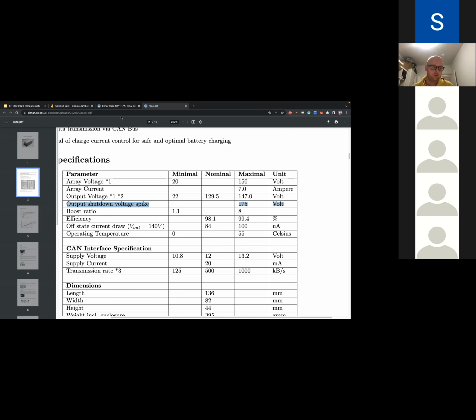I think so. Yes. Thank you. You can select your input voltage by setting a certain PWM duty cycle, and then you can sweep that input voltage to get a little IV curve graph. Then you read that graph to see where the power is highest, see what voltage corresponds to that, and try to stay on that voltage. I think I went a little quick, but hopefully that helps. It already helps, thanks a lot, Elmar. You're welcome. If you want to do a one-on-one and go into more detail, we can do that.